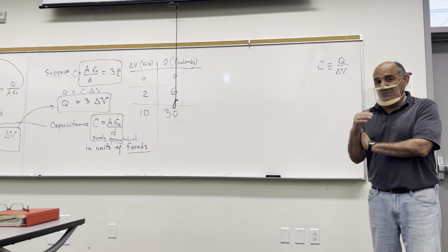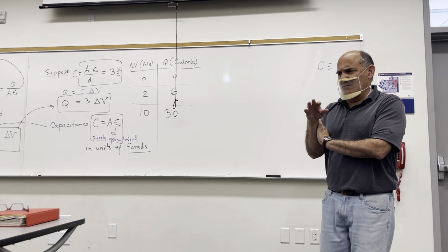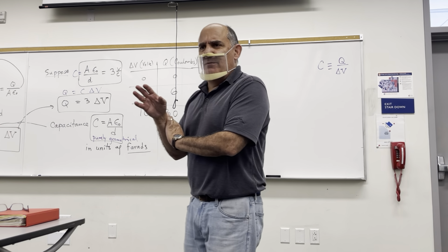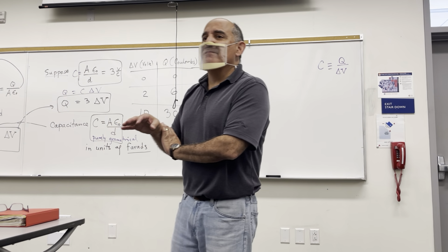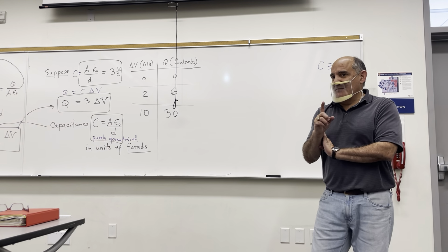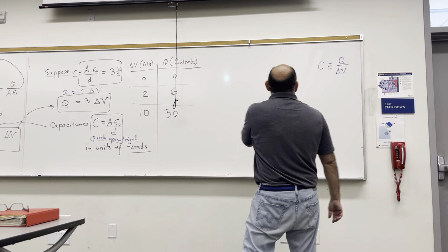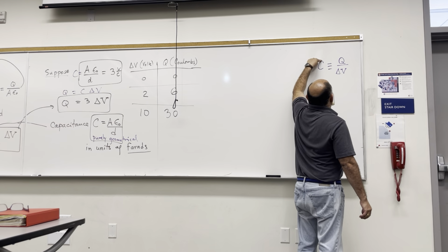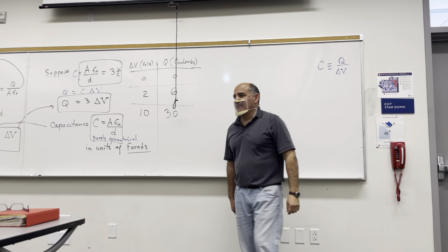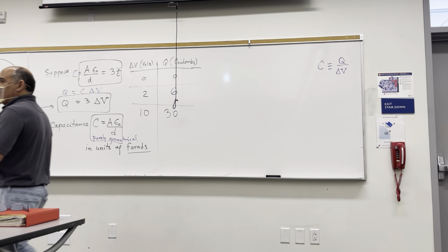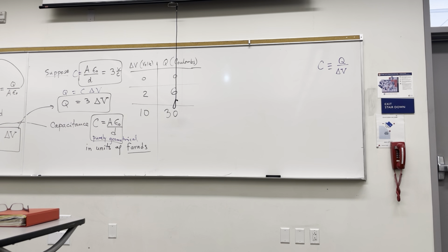You may have 4 choices, and the answer is in there. One of the options is 0, and a lot of people choose 0, because they say, oh, if there's no charge, this has to be 0. Period. But what's wrong with that reasoning? It's the wrong answer. Capacitance doesn't have a dependency on the charge, it has that dependency. So you have to remember that.